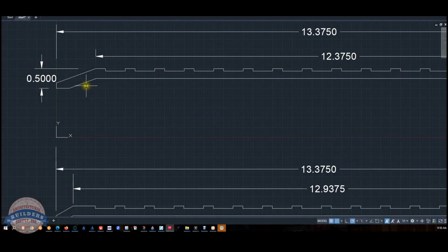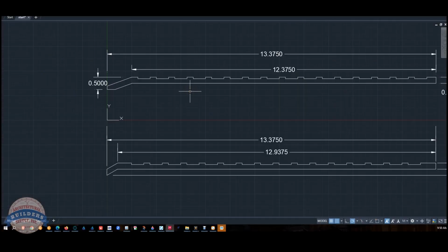We're starting with a block of aluminum. So when you visualize a 4-foot by 8-foot long sheet, half-inch plate of aluminum, how are we going to machine this? So as far as I'm concerned, we're going to put this V-bit tool path first, and then we're going to run the end mill 16 times, the entire length. Then we're going to flip the piece over, and we're going to put the V-bit here and run that, and then we're going to pocket the rest of all of this out of there.